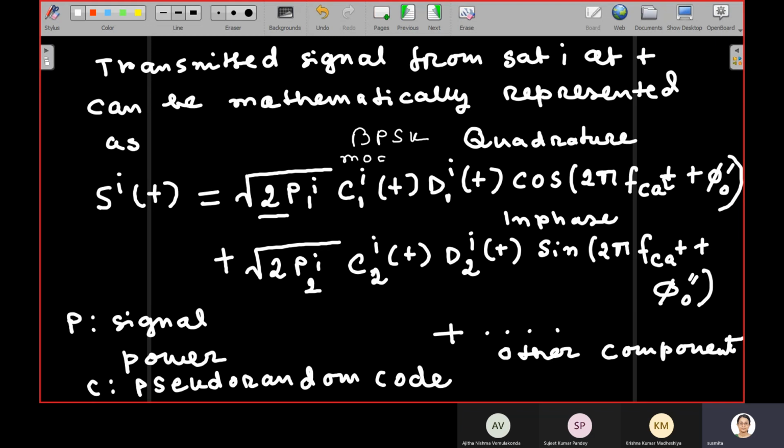If you are not familiar with this, don't feel intimidated. There is nothing great about it. You are just taking the sign plus or minus 1 and you are multiplying that to the carrier. That's all you are doing. This is called BPSK modulation. So when we multiply carrier and data this way, we are actually modulating or changing the carrier. Code and data, if we multiply this way, we are actually modulating the carrier, and in this case we have the simplest form of modulation called BPSK modulation.